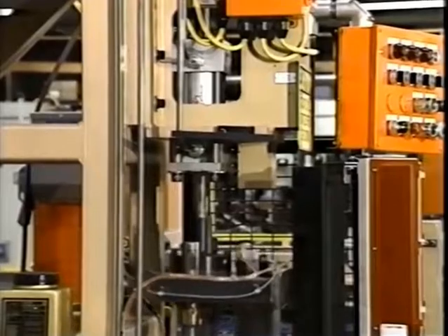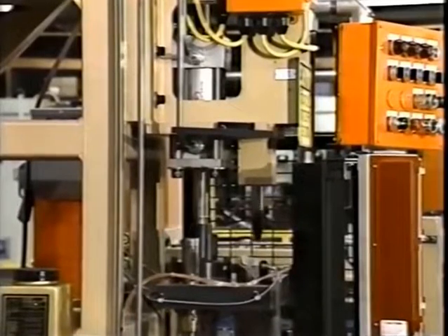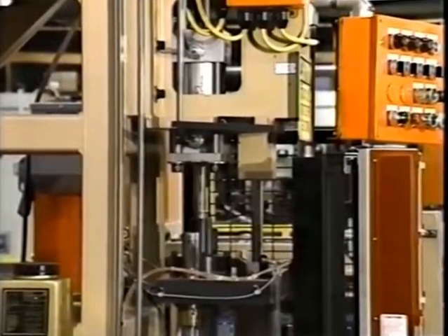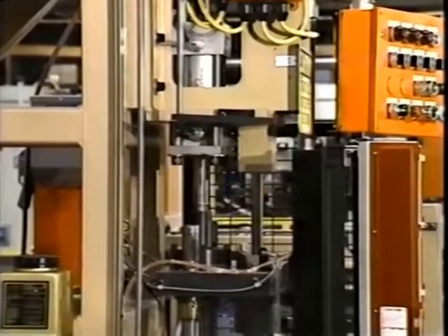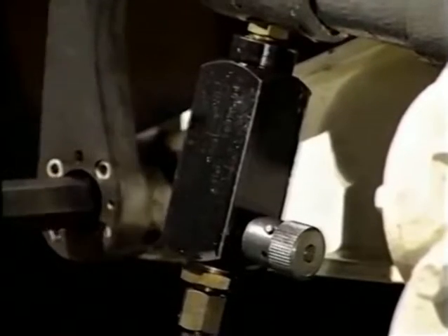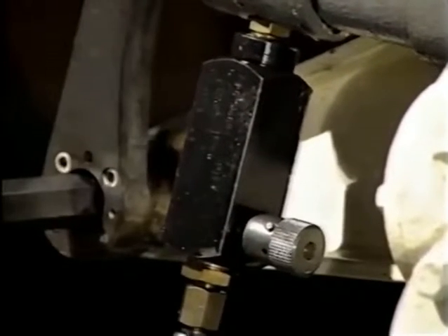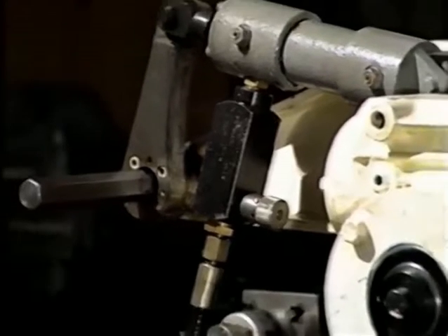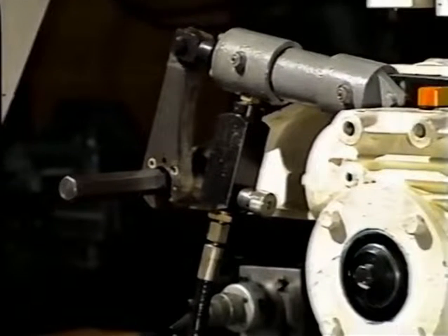However, in many hydraulic applications, the size of the pump is based on the maximum flow requirement of the system. That is, the system's peak demand. As a result, large actuators may operate too slowly, while small actuators may operate too fast. Flow control valves are used to adjust actuator velocity by adjusting the flow rate to different parts of the system.